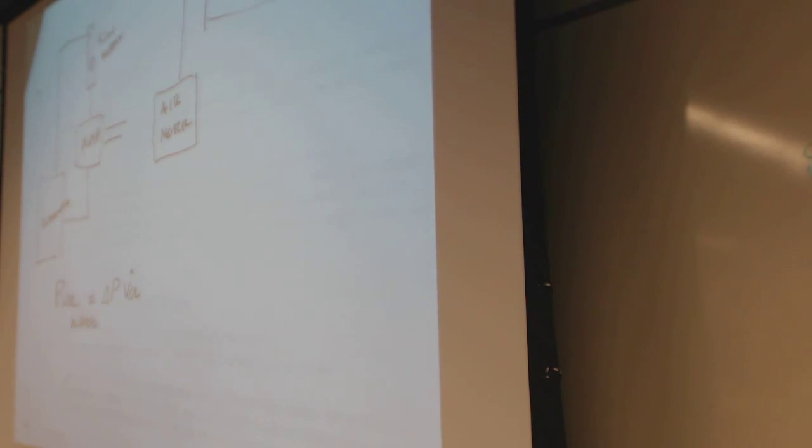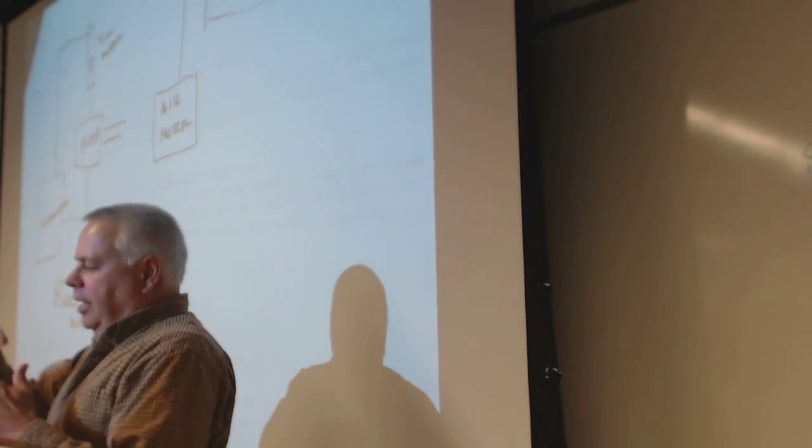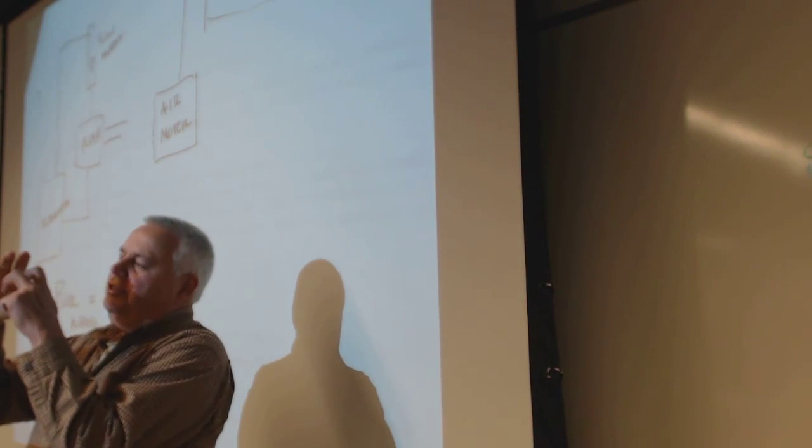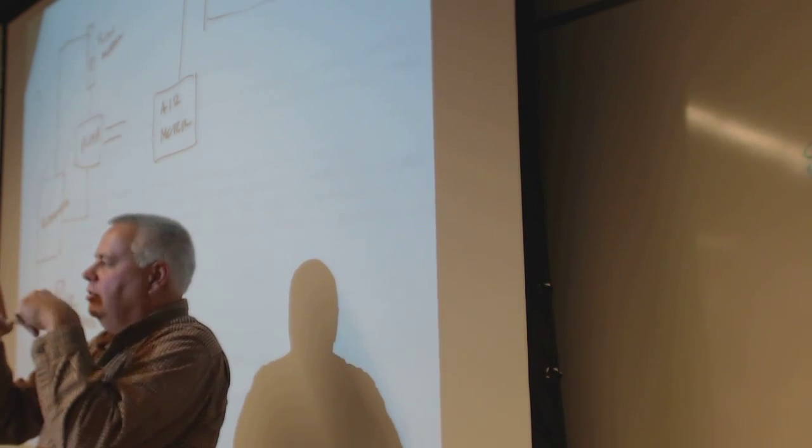On the flip side, we have an air motor. And when it's going unmuffled, it sounds like a gasoline engine or something. Put, put, put, put, put. It's a vane type motor. There's a cavity and there's a rotor, and the rotor's offset in the cavity, and there's spring-loaded plates that slide in and out as it goes around.